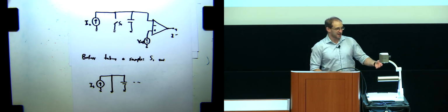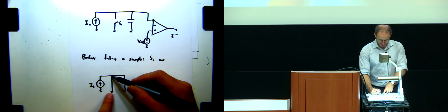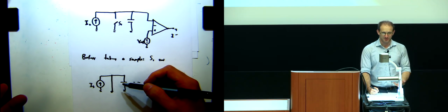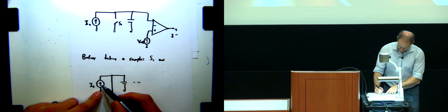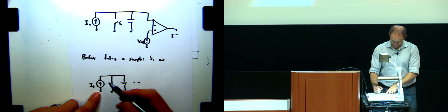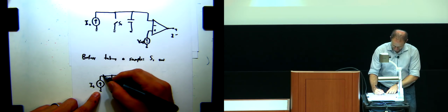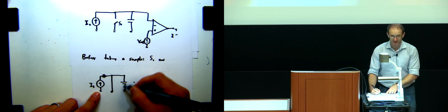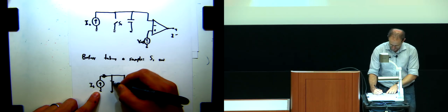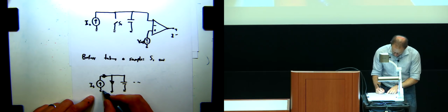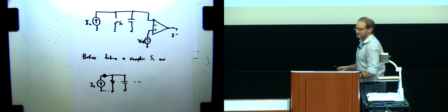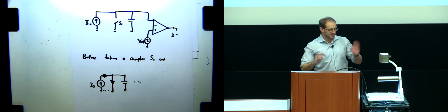If you analyze this circuit, there's a short circuit here, so the voltage across the capacitor obviously has to be 0 volts. And if you're worried about what happens to the current, don't worry. That current just comes out over here, because there's no change in voltage across the capacitor. All of that current just flows through here, and then you have to remember that the grounds are actually connected, so the loop just goes to the ground.